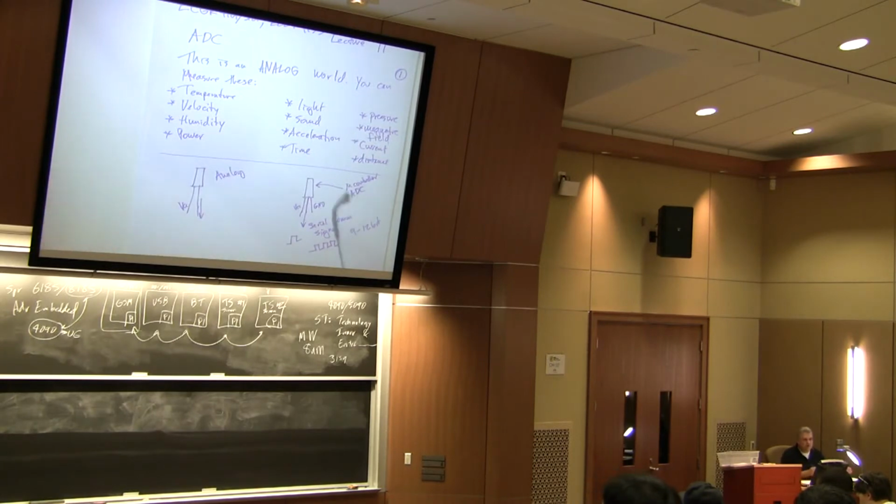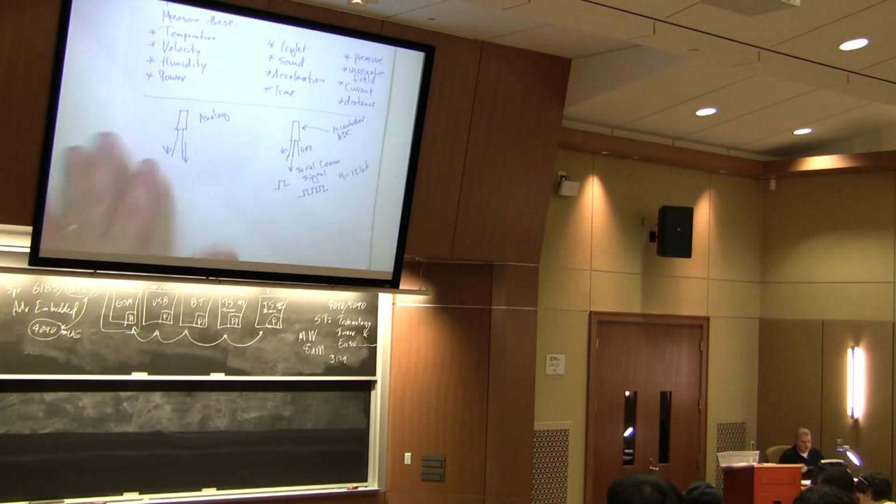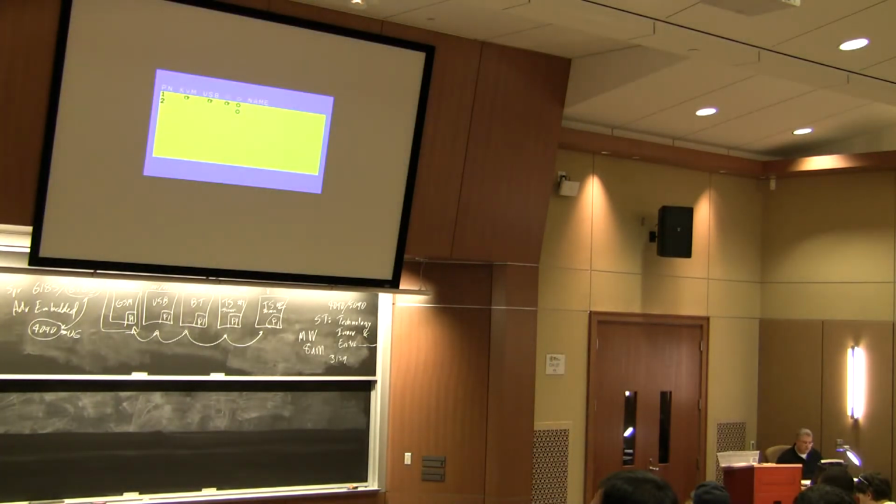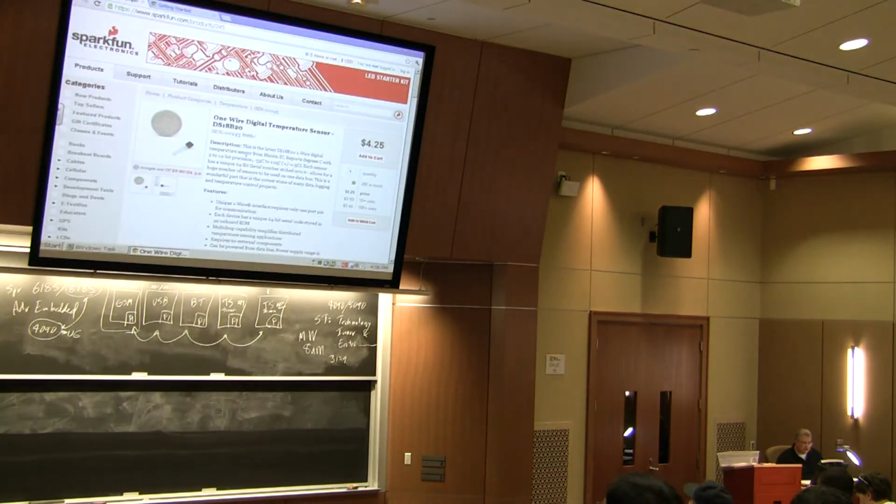And this is pretty common with the way that things are going now. By the way, if you look at this document here, it talks about one wire Maxim IC. Maxim is a company that has its own, I think it's the former Dallas Semiconductor company. It has its own protocol for communications, and it uses one single wire for the communications to be transferred back and forth. And then it needs, of course, VCC and ground.